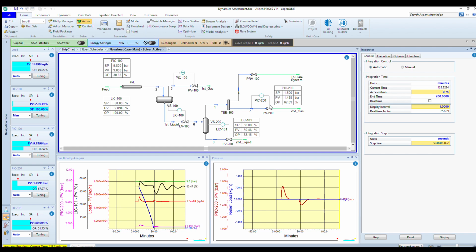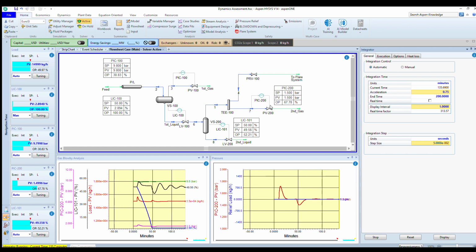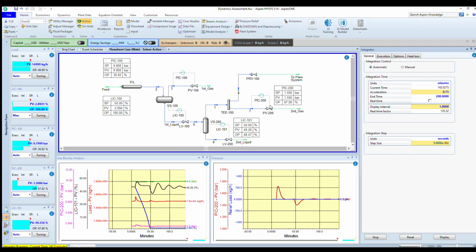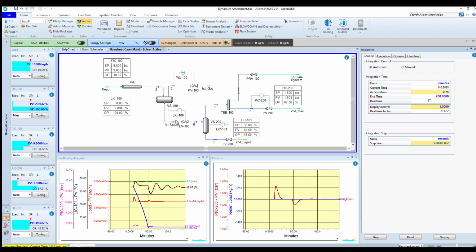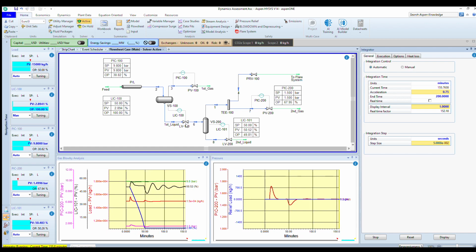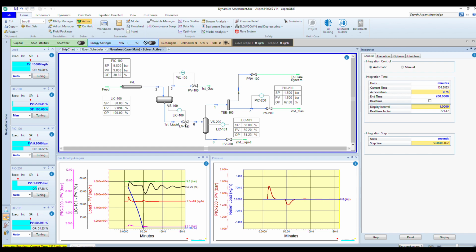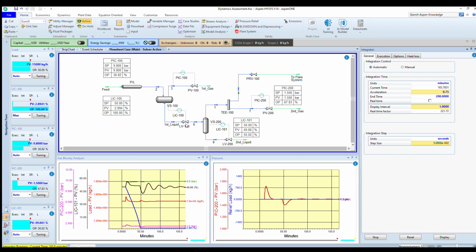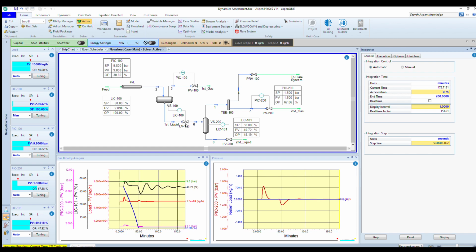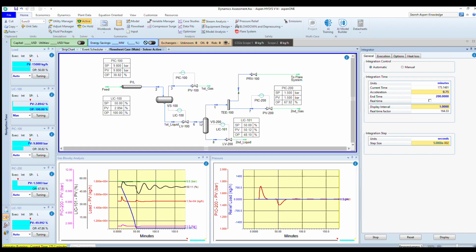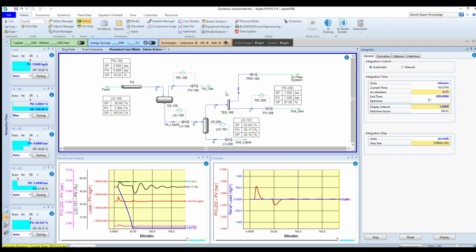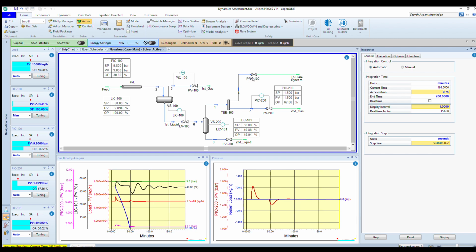But irrespective of the dynamic interactions that have taken place, I can see that though I have control valve failure, which is a credible scenario and a key initiating cause for overpressure, the dynamics has proven there is no overpressure. The pressure increase in the LP interface didn't exceed the set point of that proposed PRV.